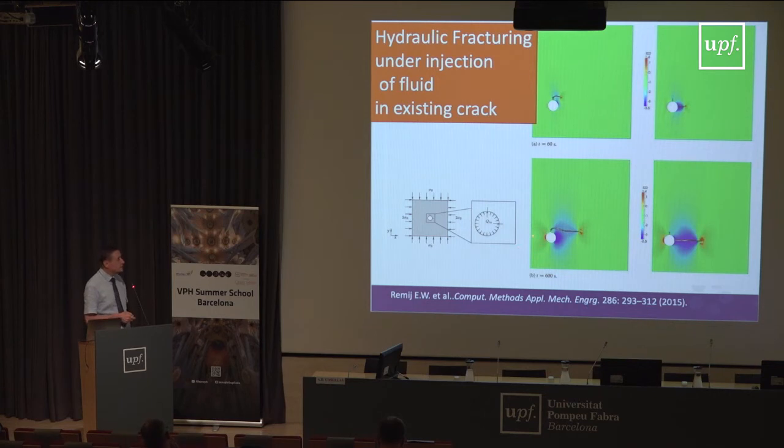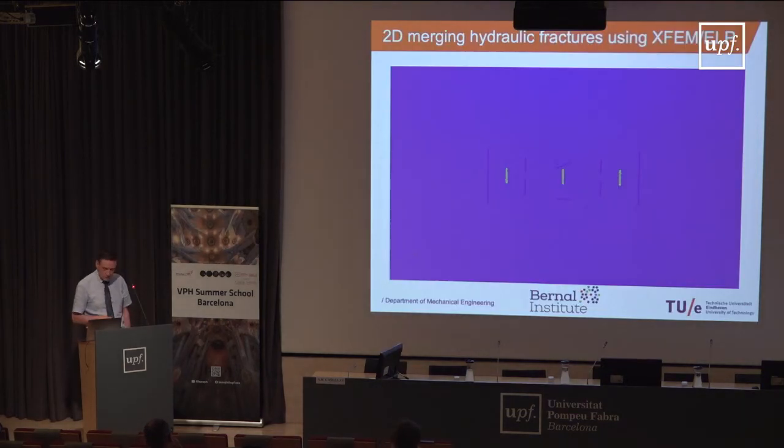And this is a simulation of a fracture propagating inside a porous medium. You can show that under gravity this fracture propagates, but typically it's going to propagate horizontally, even if you start vertically. And I can show you more simulations. This is a small initiated crack.